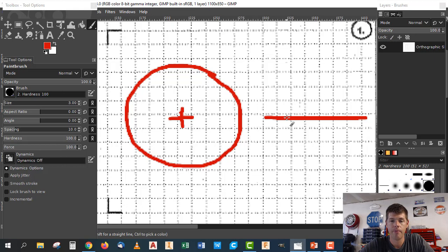And there's a specific way they would describe that. Okay? Now, you can also do it where it actually goes through and connects. So we could do that, right? Assume my line is straight here and my circle is perfectly circular. But that's an example of being coincident also. In that case, I would say the endpoint of this line is coincident with the center of the circle, okay?